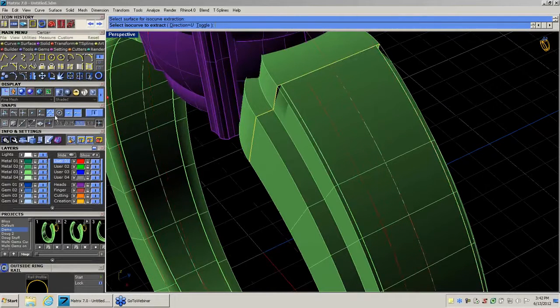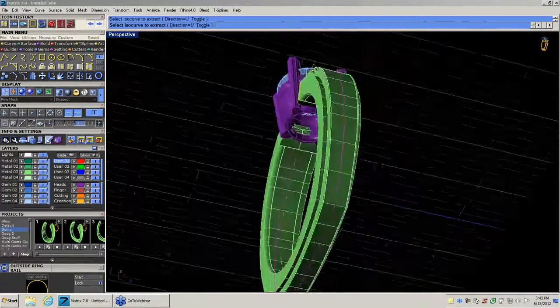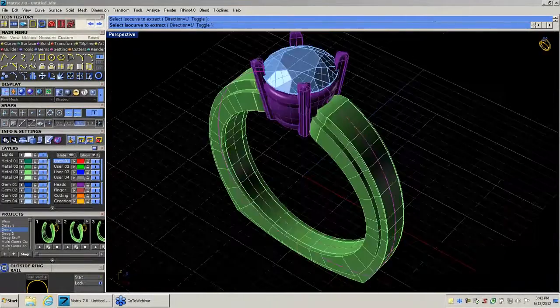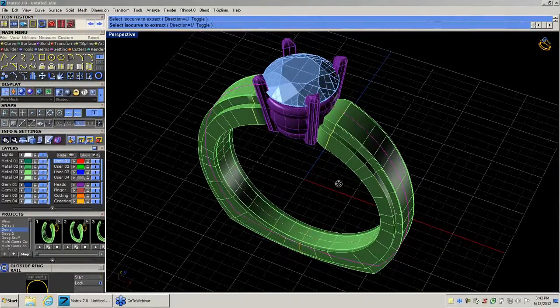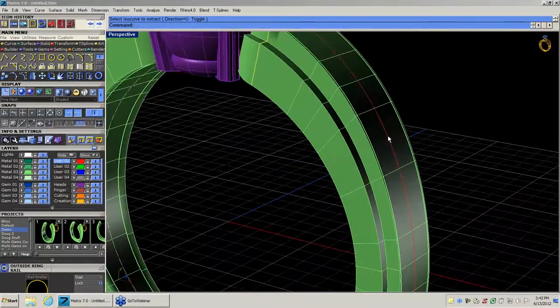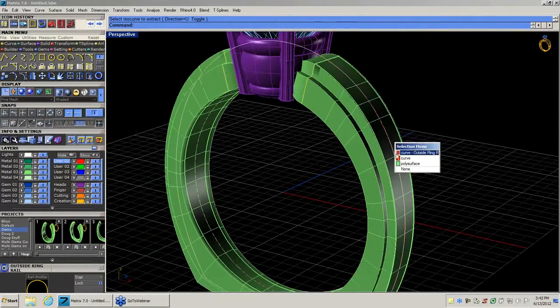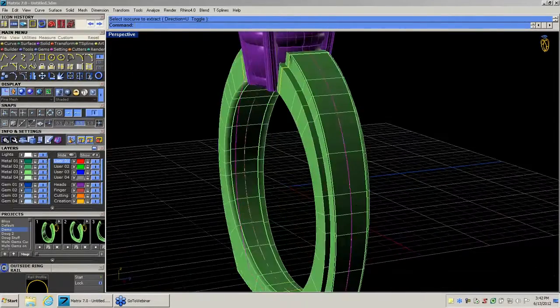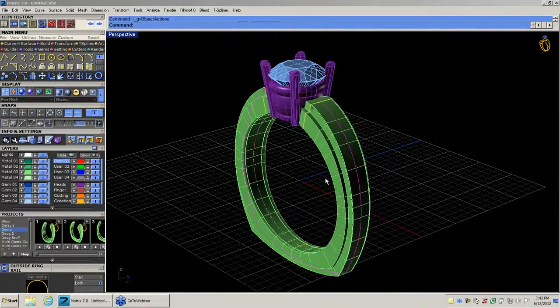And that's what I want it to do. So I snap it to the midpoint. So we have a line going all the way around there, right in the center. I put it on a different color because if I deselect that, how do I come back and get it? Well, if it's green, I'd never find it. But if it's red, I can see it.